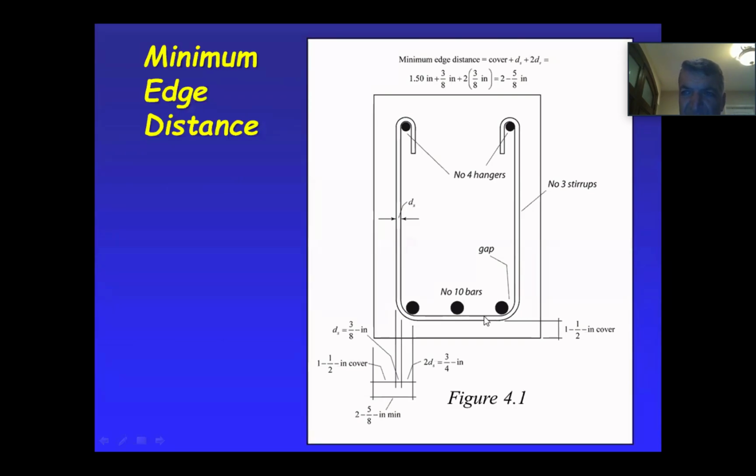So the actual cover we're talking about is really from the edge of that to the bottom. It's 1.5 inch cover, minimum. Now, the 2 inches and 2.5 and 3 inches were from the center line to the bottom. See that? So from here to there will make the difference. But when I said 2.5, if you do 2.5 or 3 inches, you're going to be able to meet this no problem. All right, so that's what that is.